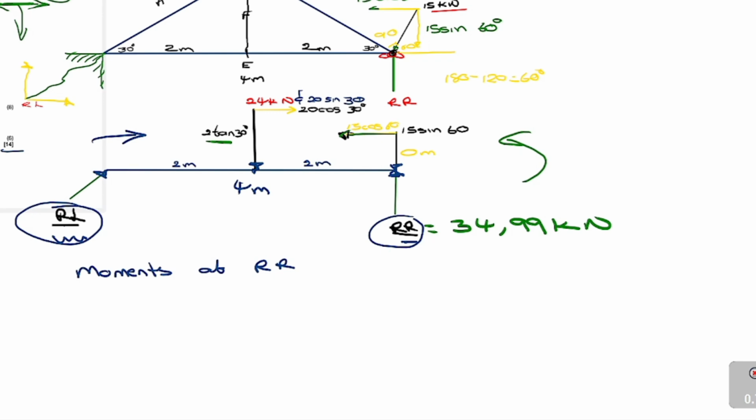But now I will say, because this is a hinge, right? It has a vertical and horizontal component, as I mentioned before. So we'll say a vertical component of what? Of RL, right? You say a vertical component of RL, or R hinge. RL is better. Okay, so what is happening with that? It is acting from here to here.